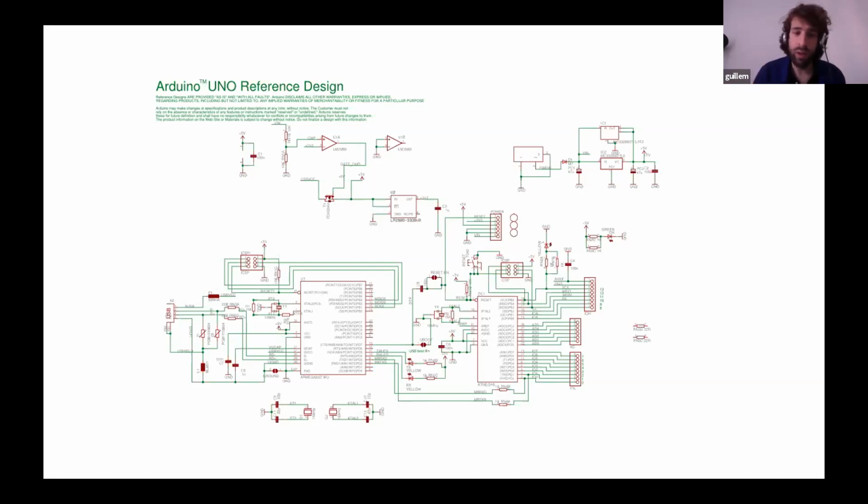And on top of that, we'll put a specific piece of software inside the ESP32, which we call the bootloader. So it can recognize code sent through USB and load that code and run it continuously. So the bootloader, in a way, is like a simple piece of code running inside our microcontroller that allows us to load code in a convenient way.